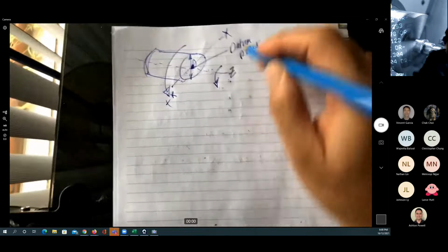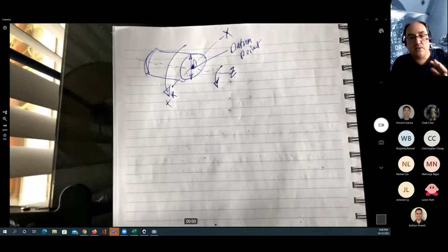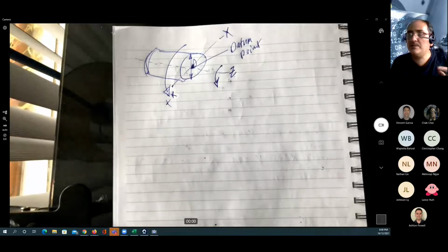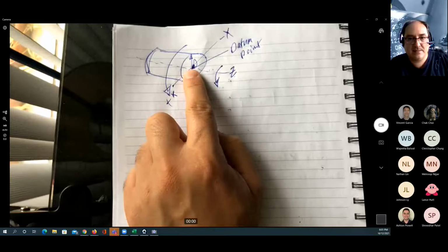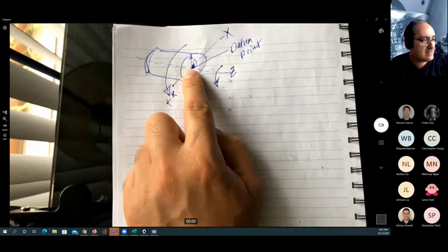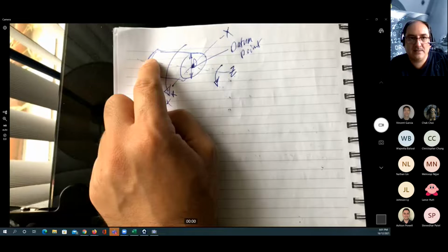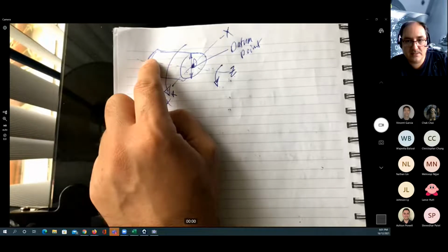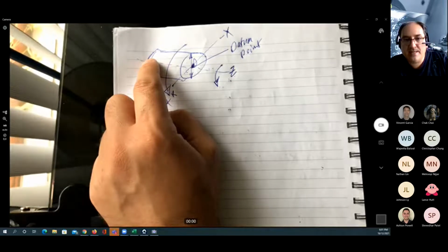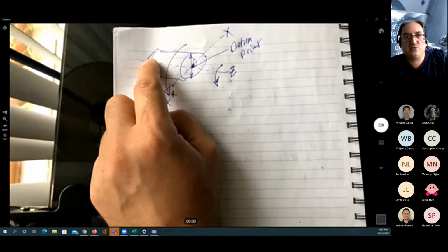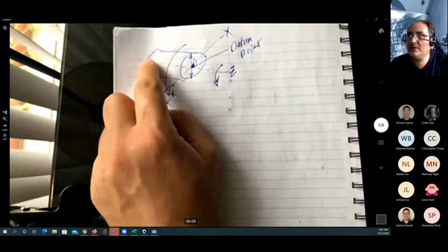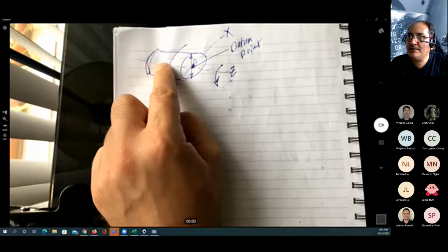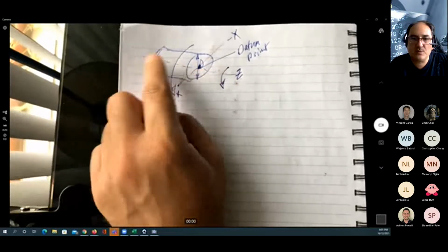In the case of the milling operation, now, some people set the datum point to be the face. Some people set it to be the end. It's up to you to say whatever you want. But you have to mention that to the machinist before you ask him to do the machining for you. Just imagine if this will be your datum point at the end there. So all the data you're going to give for the z-axis is going to be positive value.